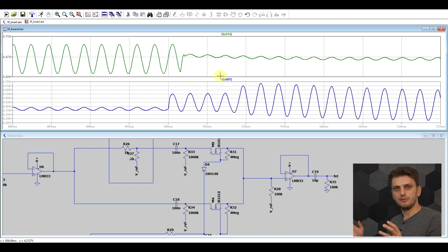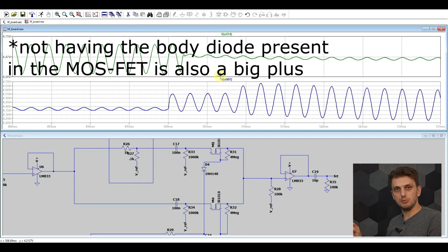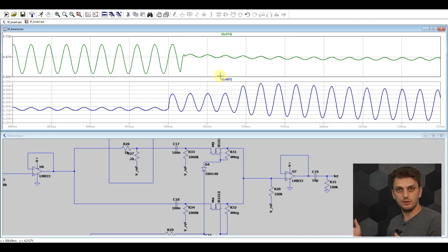So basically the main advantage of using the JFETs as analog switches is the smooth transitioning between one signal and the other. By using that sort of transistor, you can keep playing and then just switch in between the affected and unaffected sounds without causing any sort of audio discomfort. Speaking of audio discomfort, let's quickly listen to how the two sounds actually sound.